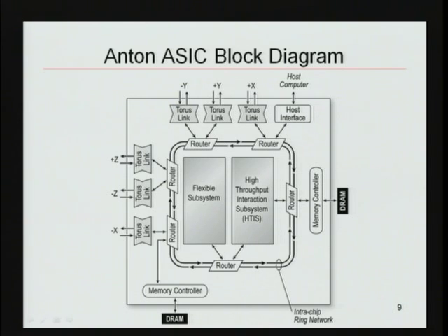And they also interconnect to the 6 high-speed links, which are parallel high-speed channels, each one of which is running at 5 gigabit per second per wire, and has total bandwidth of approximately 12 gigabytes per second per channel.